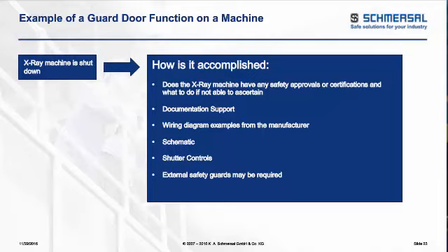Part of that might be putting shutters over the X-ray with proper lead protection that has its own set of safety switches on it, so you have to make sure the shutters are closed and approved before you allow power to even go to that laser, if you're not able to substantiate and back up via documentation that that X-ray controller or that laser marking controller meets a certain safety standard.